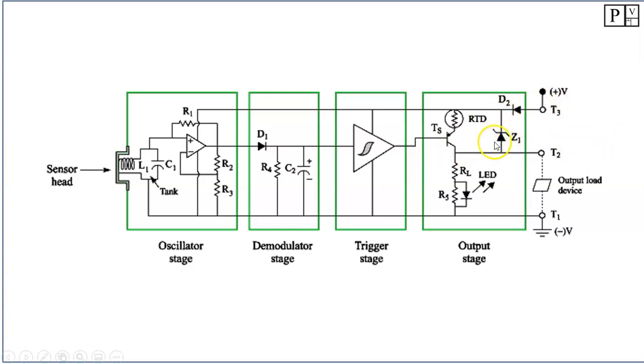Well, a zener is there so that it shorts out or bypasses the transistor. A zener in forward bias normally acts as a diode, but if you put it in reverse bias, it acts as a voltage sensitive switch. So if the voltage gets too high, then this guy starts to conduct and it bypasses the transistor, again, hopefully stopping that guy from being smoked. So overcurrent, transient noise or over voltage, and then reverse polarity.